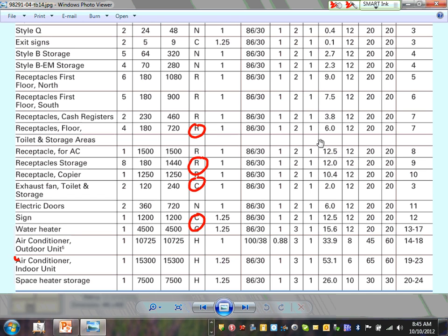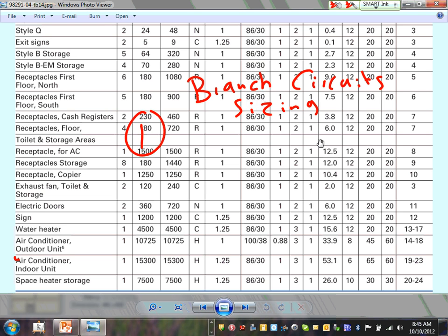Lump sum them. I can't emphasize this enough. I'm going to write them down here, guys. When you size branch circuits, there are 3 calculations you have to do. Number 1 is continuous: if it's continuous, 1.25 times the I, and you size it.